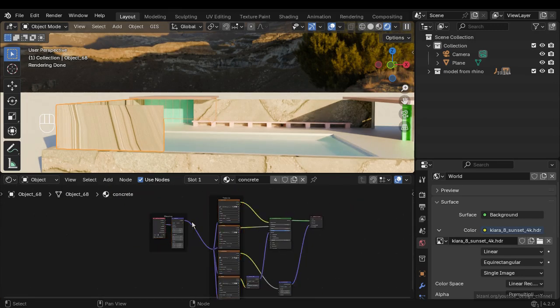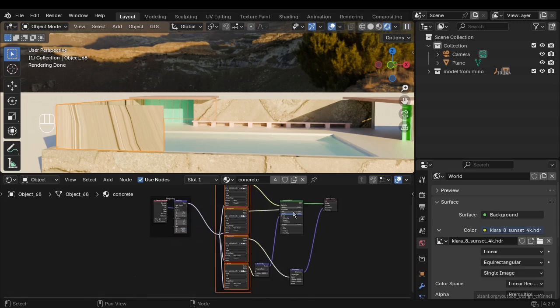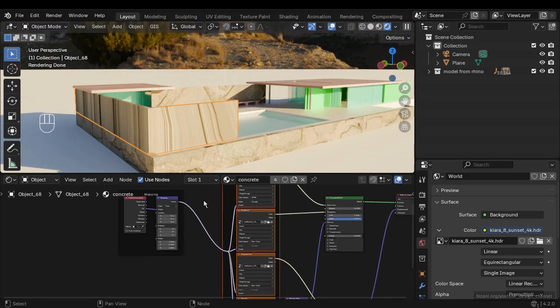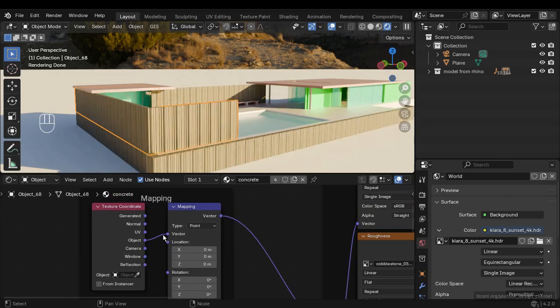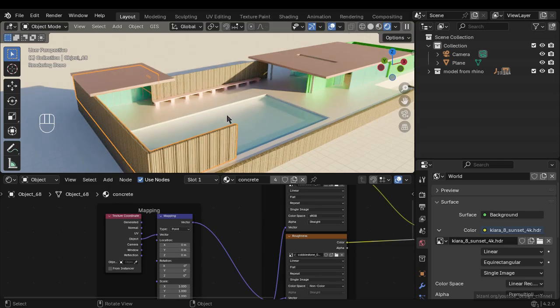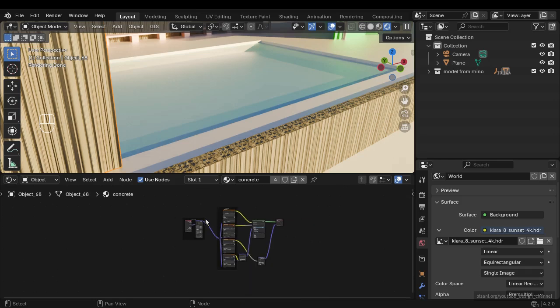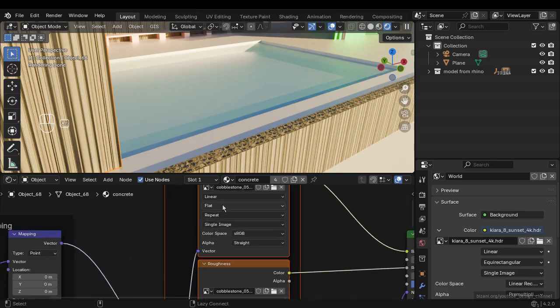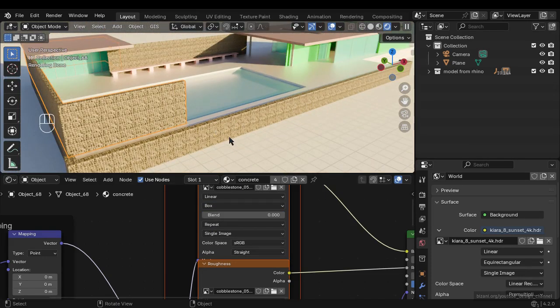So we have the texture mapping, and these are the different textures, and all the nodes are already set up. But as we can see, the mapping here is not set. The basic texture mapping is flat, which is just the object projecting from the top to the bottom. As you can see, we start having something here, but we have to select all of these, press Alt, and change Flat to Box. And now it's projected orthogonally in the 3 axes.